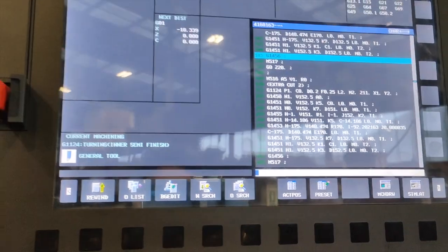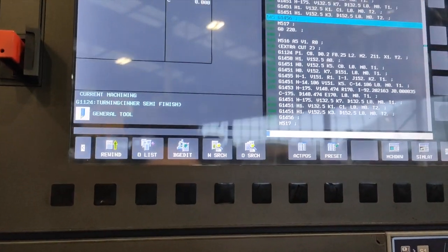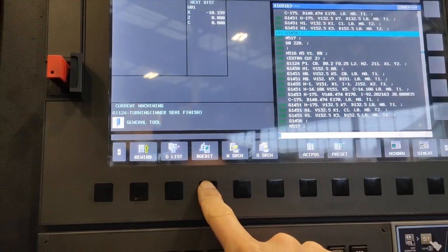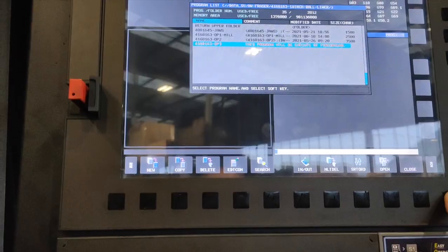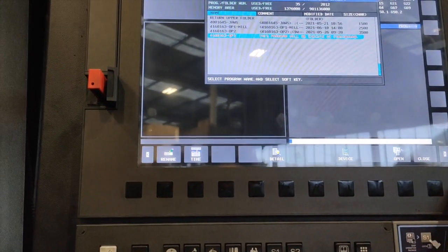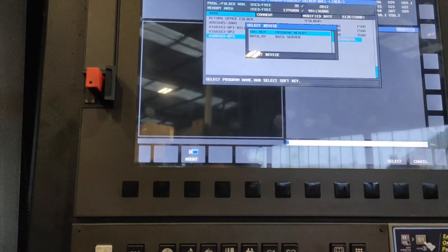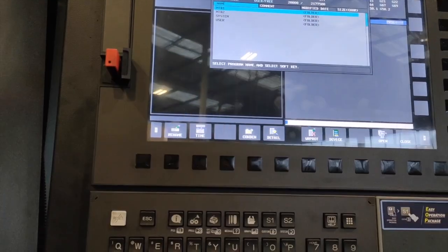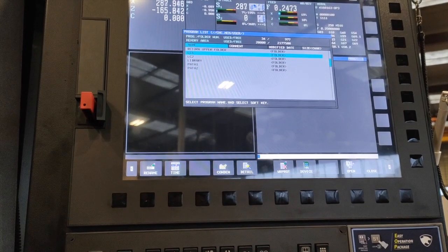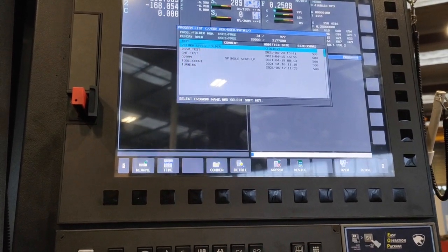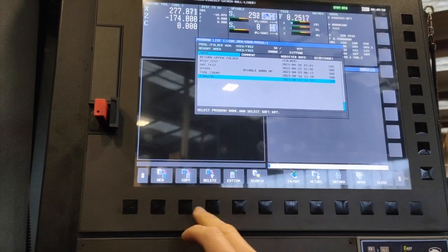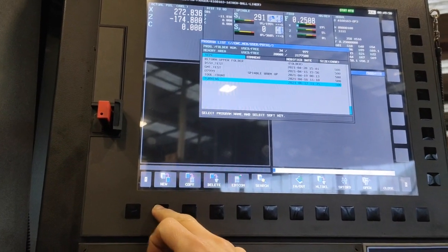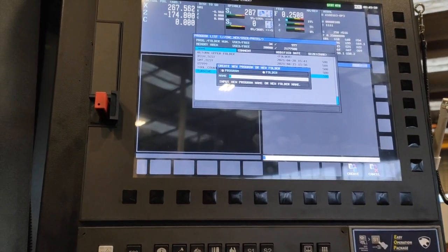Okay guys, so my machine is running, and I will take this opportunity to show you how to program a lathe machine. The first thing we are going to do is go to background edit. Since my program is on the data server, I will use the CNC memory. Select, go to user and path number 1, and I'm going to create a program, say simple turning.